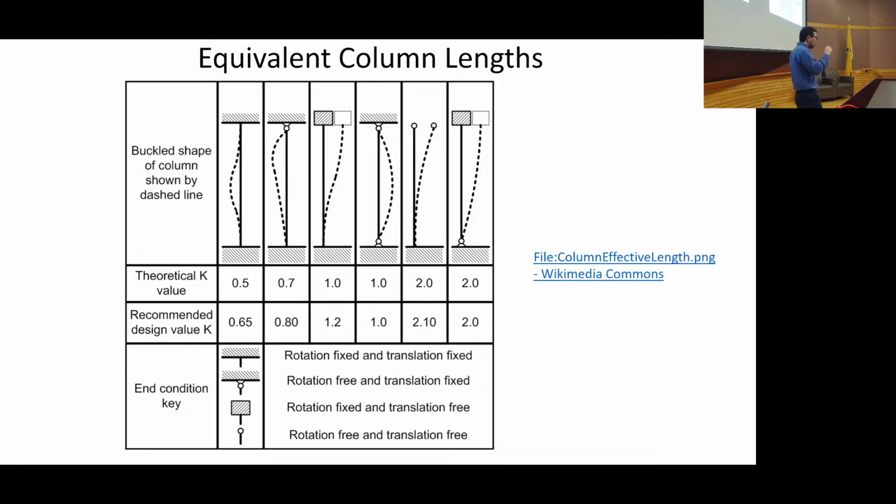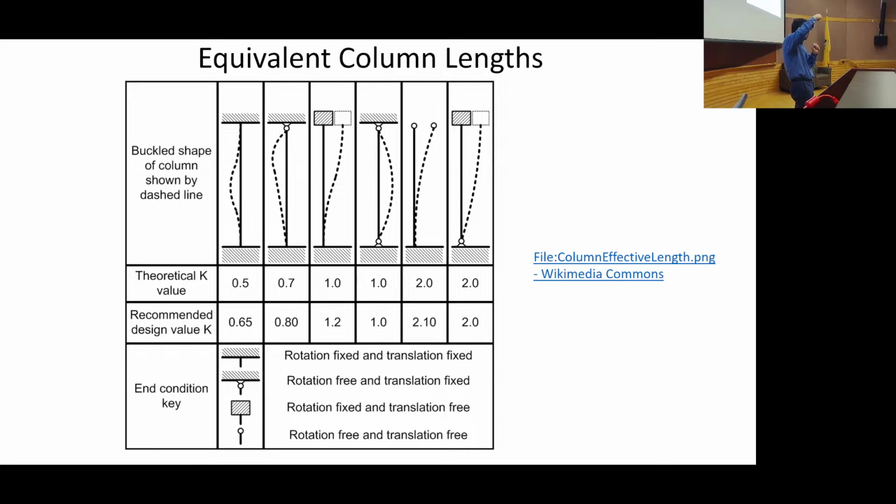Lost the thought. So coming back to this, the equivalent column length, buckling is going to be dependent on the length as well. And since we're talking about a system that has an elastic instability where it flows out, orthogonal to the direction I might be compressing, how I hold it at the ends is going to make a difference. So if I'm trying to make sure that it doesn't bow out, with my constraints laterally and with moment, I guess that's not even a word, right?